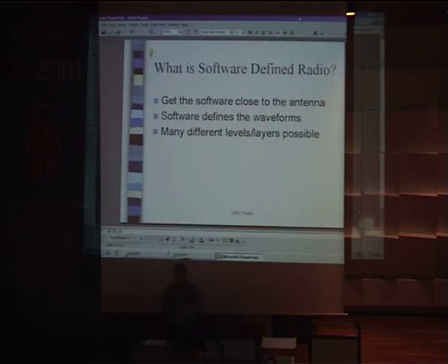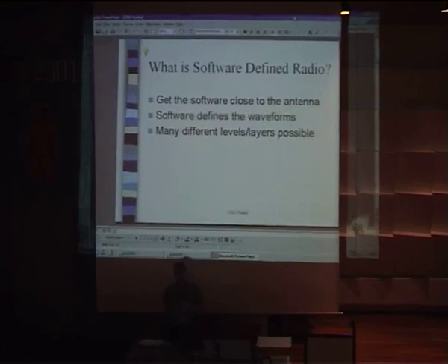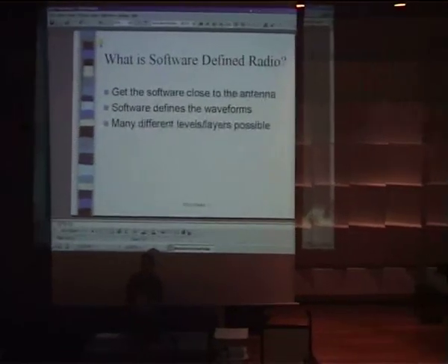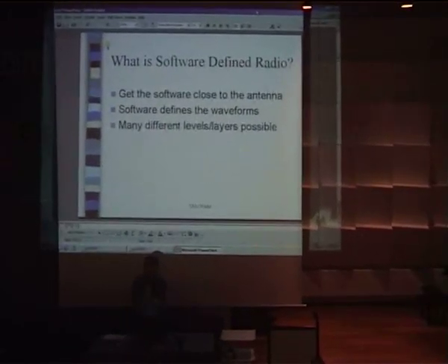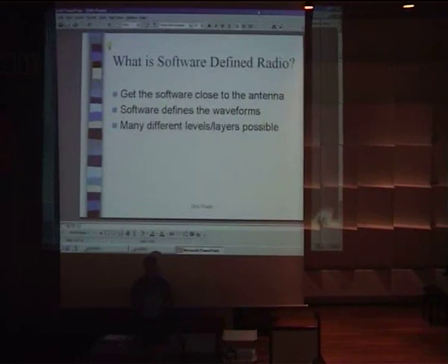The other thing about software-defined radio is that the software continues to define the actual waveform. So there's this whole spectrum you can look at, where there are processors and there are radios, and where do I draw this boundary? We'll cover that in some detail later on. But you can start with a conventional analog radio, like for home use, an FM receiver, which is fundamentally an analog receiver. It may have a digital display on it. It may have a digital PLL that sets the frequencies, but fundamentally it's an analog device that has some digital control on it.